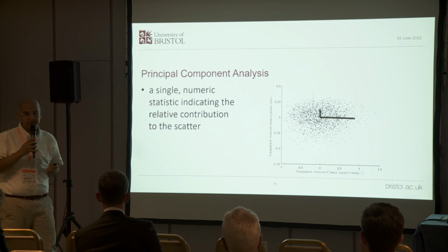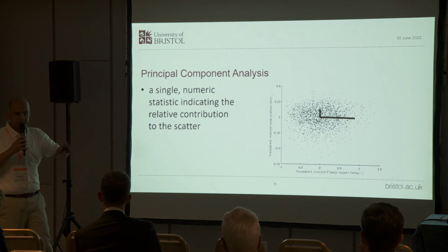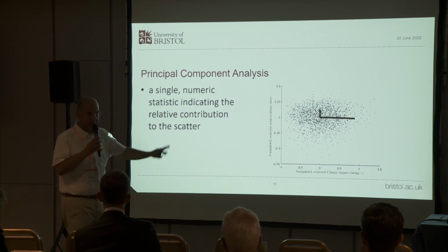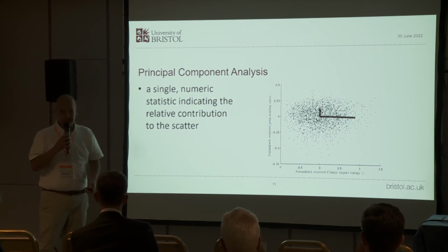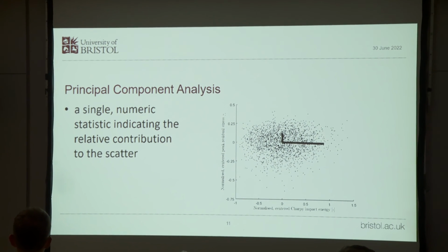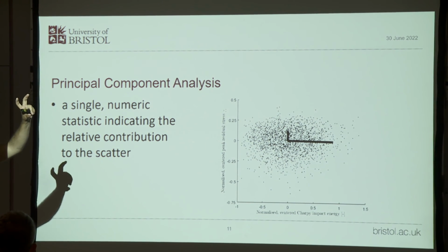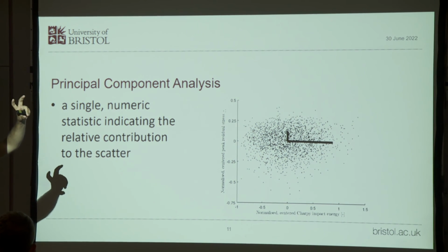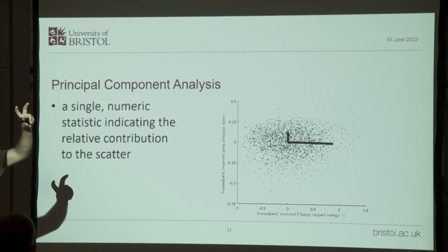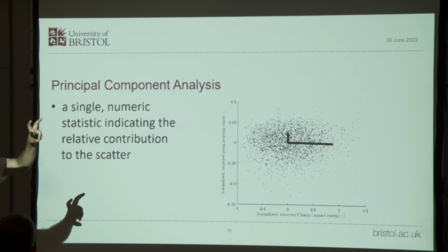You get a really clever PhD student, and he spends a year studying statistics, although he's doing a mechanical engineering weld project. And he comes up with principal component analysis, which can tell us, I have a variability in my material, let's call it fracture toughness. There are two components that cause this variability, the variability in the microstructure and the variability in the residual stress.